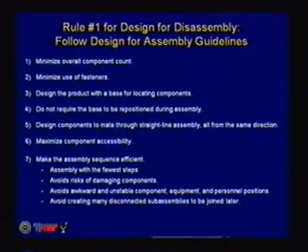People say, use snap fits all the time for design for disassembly. I go bananas when I hear that, and a couple of you know this very well. Look at a cell phone. Try to take your cell phone apart. It probably has a snap fit, a lot of them do anyway, and they're a real pain in the neck if you don't have access to that third direction to pull it out.